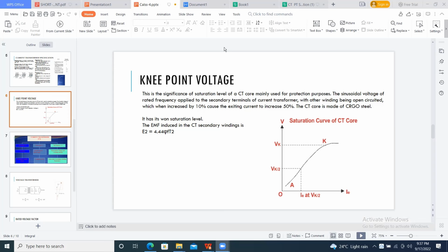From the relay point of view, the protection class, you are not much worried about the relay. You are worried that the through fault current, the maximum fault current seen by the CT, should be less than the current at which the CT enters saturation. Because the principle of a protection CT is to protect the system, and it should not operate for faults in other zones. Understood?